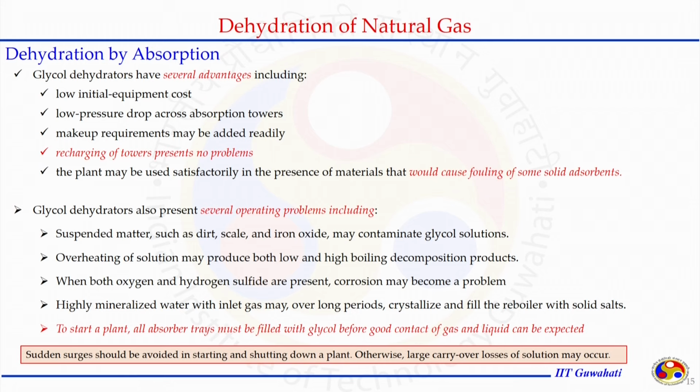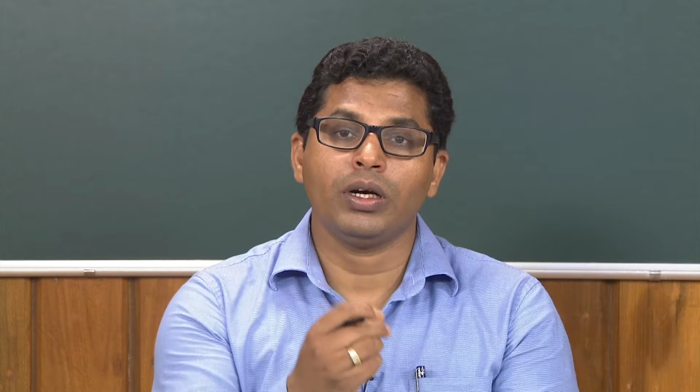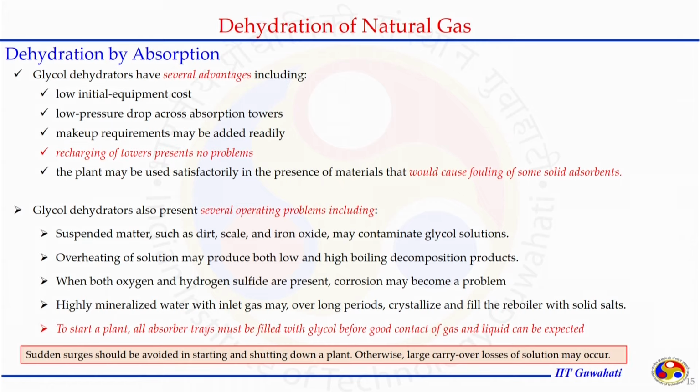So, if the water that is present, which also has some significant minerals in it, gets separated from the glycol, goes through the flash separator, then to the heat exchanger, and finally to the reboiler, where the water gets out because of the evaporation process, those minerals will remain in the glycol phase, and if that is the case, they may create a problem.